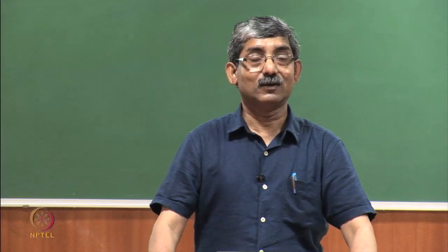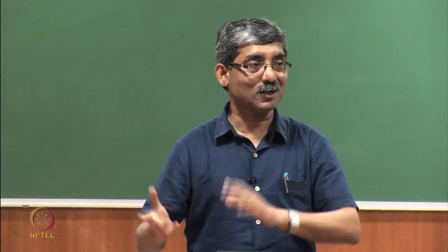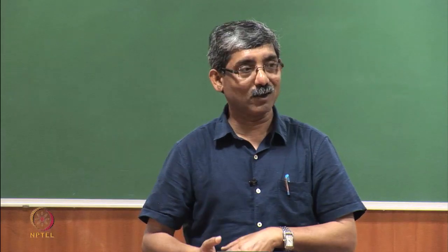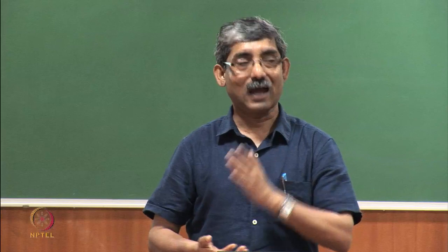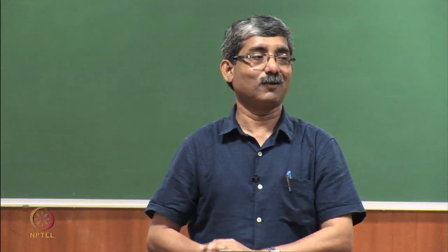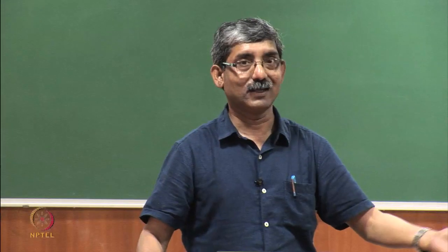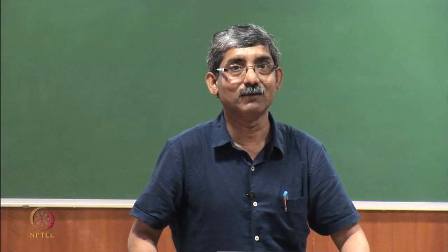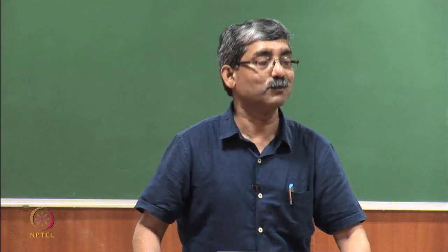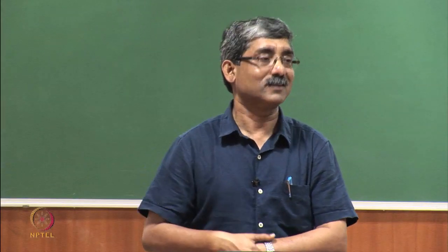What does it mean? It is a combination of Young's modulus, the diameter of the fiber and the length of the fiber. If we have a coarser fiber but use a longer length, effectively our buckling force will be less, so it may not give the prickle sensation.